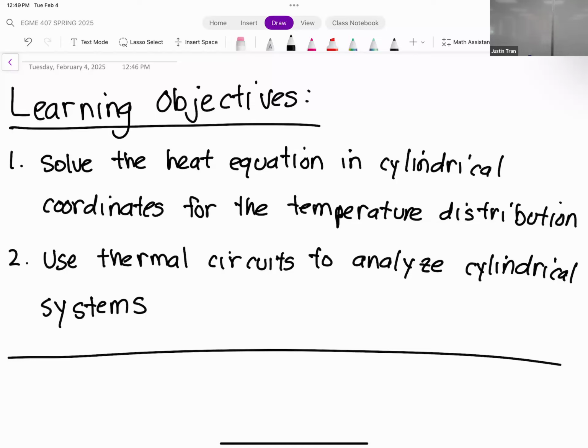There's only four. So, okay, the heater itself, we assume it's strong with the bigger so you can see it, but in reality it's really thin. So there's no resistance there, but there is heat being generated. So you have two resistances for the conduction of the solid walls and two resistances for the convection, and you have heat coming in on the right side.